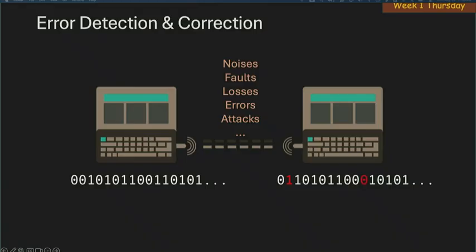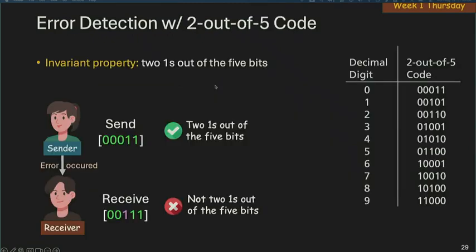Let's say for credit card, remember that example. For credit card, I only want detection but not correction, for safety reasons. For communication, it could be either detection or correction, depending on the security or sensitivity level of that communication protocol. 2 out of 5 code has the error detection capability. Correct codes have 2 ones. Incorrect codes would have a single 1, 3 ones, 4 ones, 5 ones. But whenever I see anything but 2 ones in my 5-bit message, I know that it is not correct.